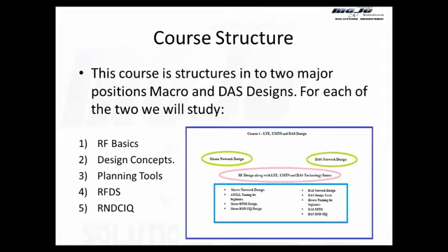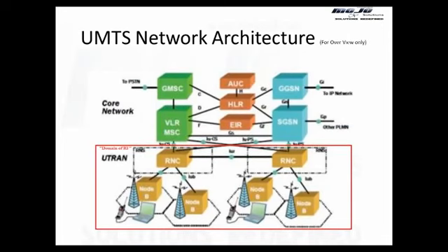So what this course is doing is getting you RF basics, giving you design concepts, and getting you an introduction to, and very close to, hands-on knowledge of planning tools, but not hands-on knowledge. You will know how to prepare an RFDS for any macro, DAS, 2C, 3C sites, and the RND-CIQ, how the RND-CIQ is prepared, and what its role is in this overall design process.